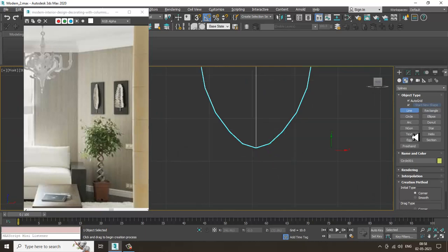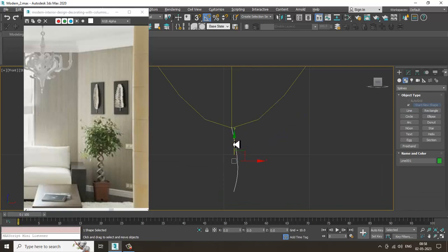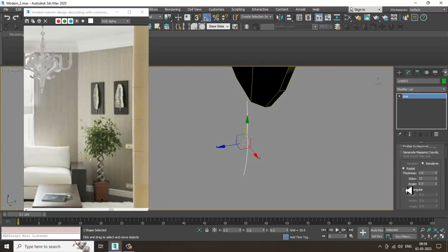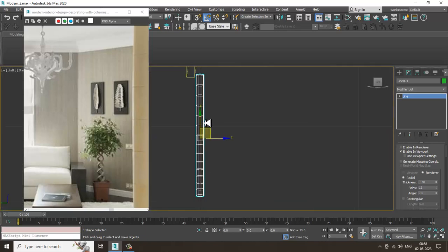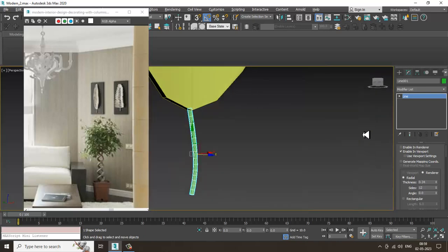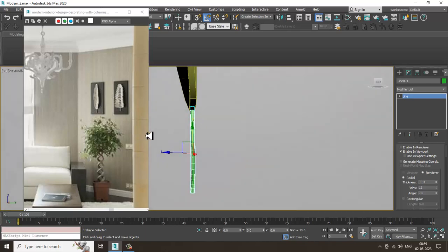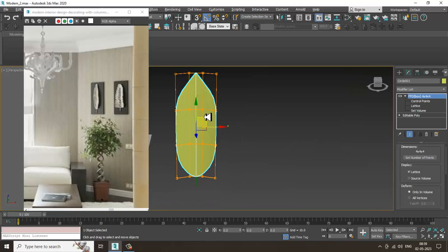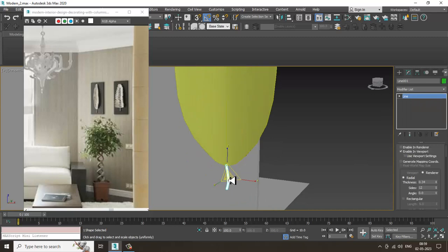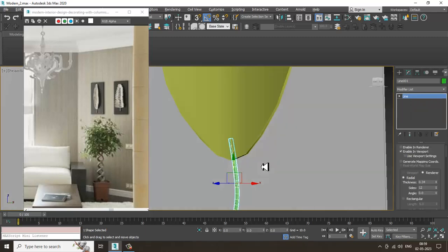Again let's take a line. I'll just off this auto grid over here in this way. Slightly just push it over here and enable in viewport, reduce its thickness. Again go over here and slightly push it up over here in this way. So once this is done, I can again go into this control points, slightly I can just scale it, and if you want I can slightly scale it in this way.